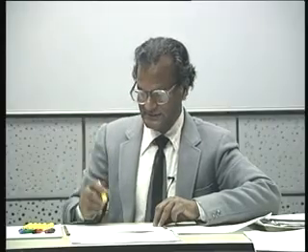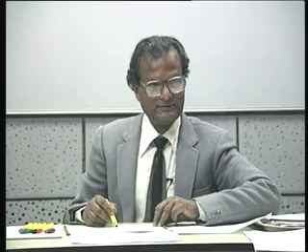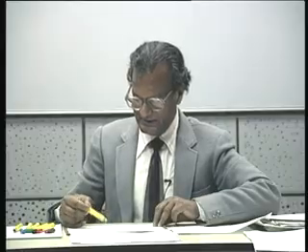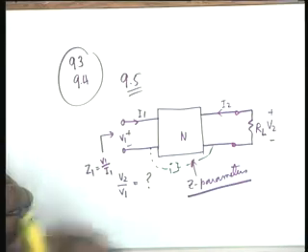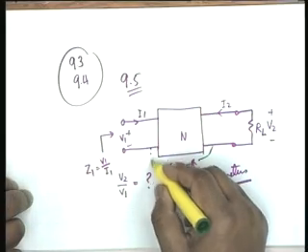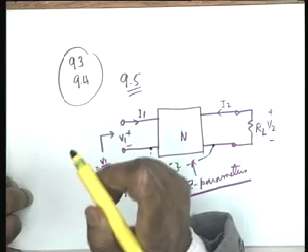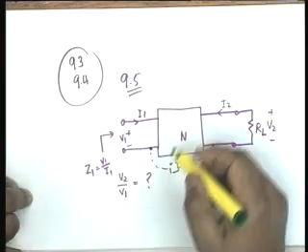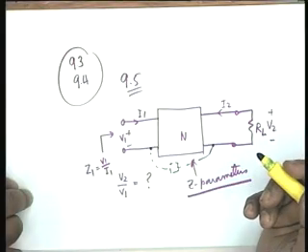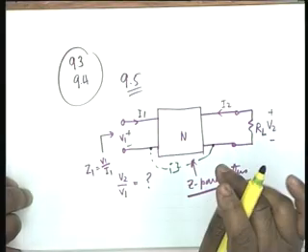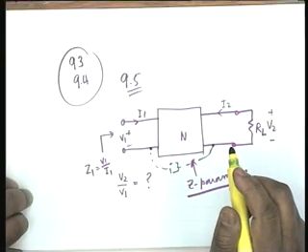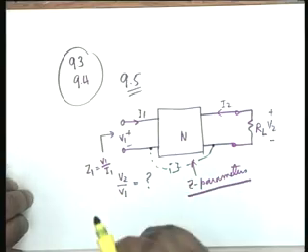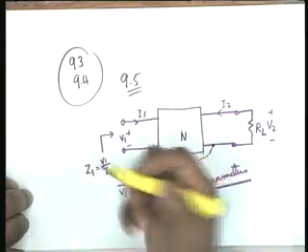Alright. Suppose the network, now mind my words very carefully, suppose the network had a bridging element here. Suppose we had something like this. Also, in addition to this RL, there was a bridging element here from here to here. Could we use the T parameter equivalent circuit? No, because then this element would have been short circuited. There is no such possibility of a calamity here, and therefore we can indeed use the T parameters. Alright, we can use, but as I said, it has to be used with caution. I have given you one situation where it cannot be used.